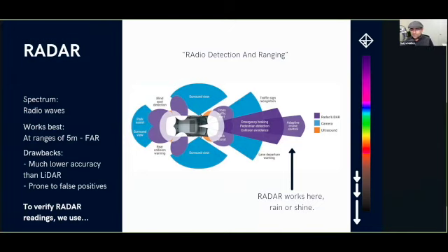What about ultrasound? What is that used for? Yeah, so basically ultrasound will work the same way, but the way I understand it is that it works at close distances because it doesn't go very far. There's just a lot more interference for ultrasound. So in an autonomous vehicle context, what you'll use it for is making sure the vehicle isn't right next to you, right? This is also the sensor you see in Lego Mindstorms. It only has so much distance, but the readings it does give you are accurate. Okay.